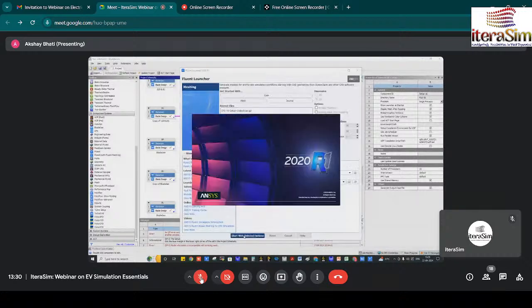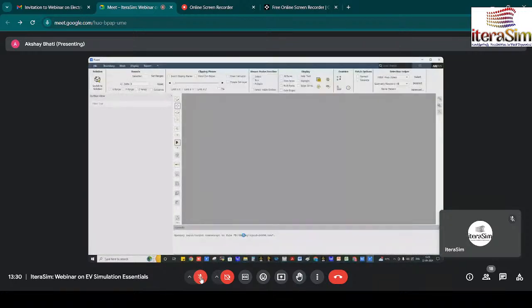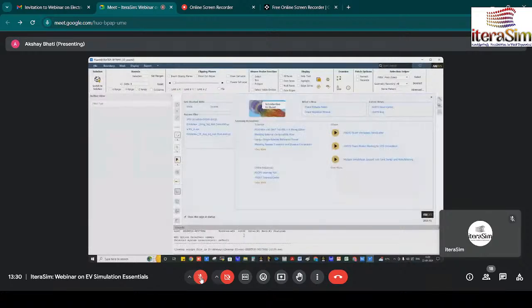Yeah, I will show you how we can develop the mesh in Fluent directly, because in Workbench meshing it takes a lot of time and also increases the mesh count. But in Fluent it develops a polyhedral mesh, so it is easy to generate. However, your geometry should be properly clean, with no extra edges and no interference. Otherwise it will get stuck somewhere in meshing. But if you think your geometry is properly clean, you can go directly to Fluent meshing. It is easy.